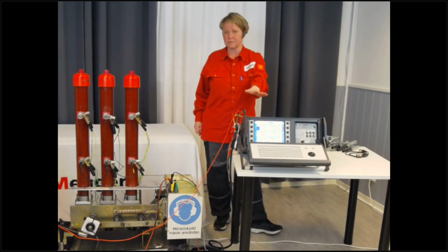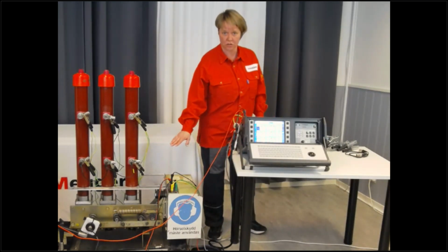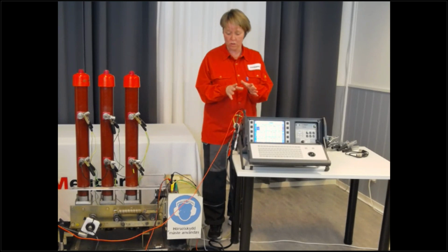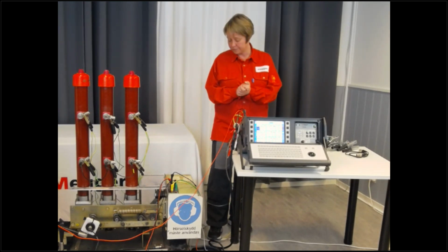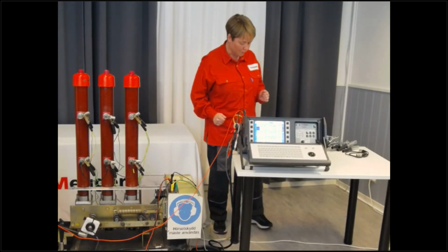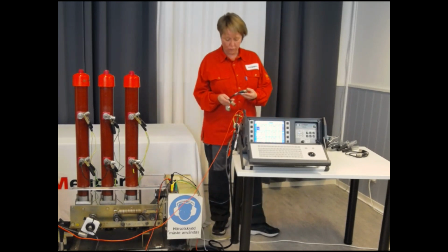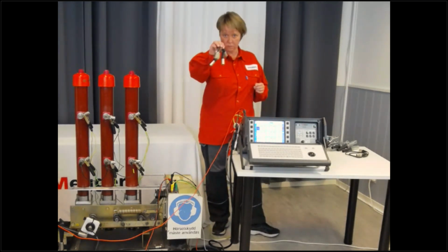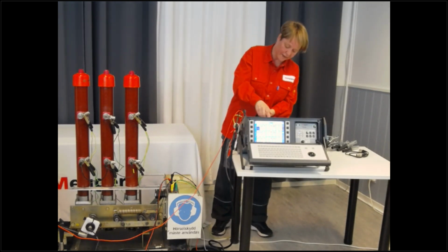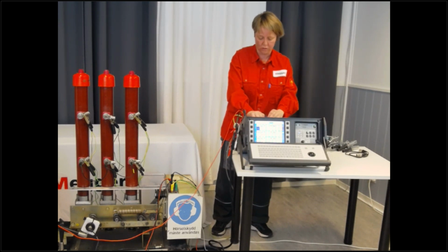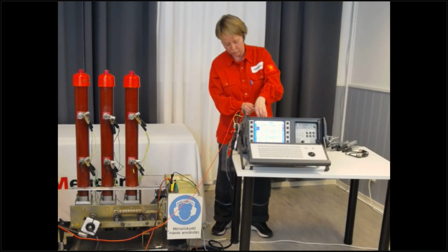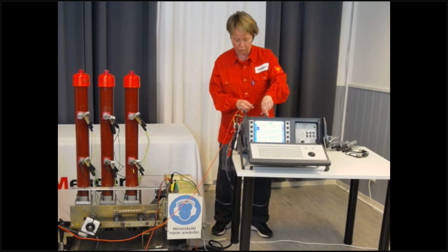With TM 1800 and TM 1700, the auxiliary contacts in the circuit of the breaker are measured automatically by the control module. So the control module here is more advanced than with Eagle. So I don't need to do the connections for that. But I need to prepare to do the dual ground. And for that I need to connect one extra cable. It's a very odd one. It looks like this. That's a link between two modules. We don't want to lock the MR module to only being able to do DCM, dual ground, but we want it to be flexible. So instead we use a cable.